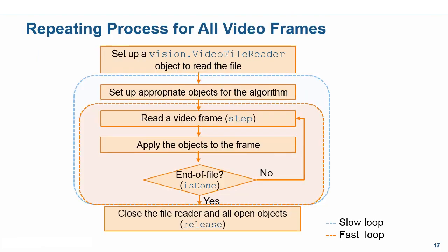We then talked about how to implement this in a loop for a video instead of a static image. This was similar to the video file reader example in the import video. Setting up system objects and necessary variables is the first step. Then we used a combination of functions and step on system objects to perform the computer vision algorithm. Finally, we released all the system objects in use.